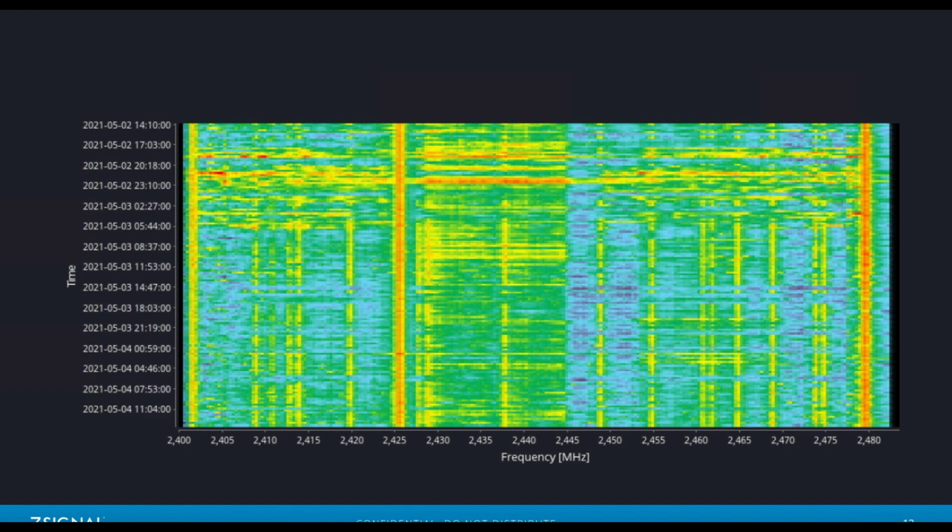And then, if you look at the background, there's sort of, in the lighter cyan, a bit of a washboard effect. That looks like Bluetooth, the frequency hopping that classic Bluetooth will do. But you also have those narrowband channels that are quite a bit louder, and they're being utilized much more frequently. So I'm not exactly sure what that is. There's certainly Bluetooth going on.